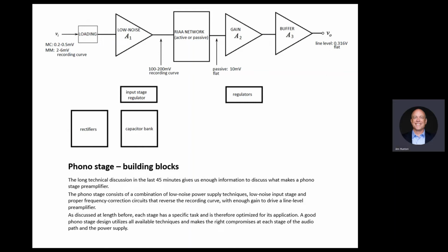And from that point on, we're just amplifying. This is not phono anymore. This is now amplifiers or a preamp. So maybe one stage, maybe two stages. And then we have the issue of going out into the real world load. Some of them buffer more. Some, especially tubes, will put a cathode follower circuit. It's a circuit that lowers the output resistance, so you can drive more cable. Each one of those circuits has its own characteristics. Low noise in the beginning, high drive on the output, frequency response in the middle.